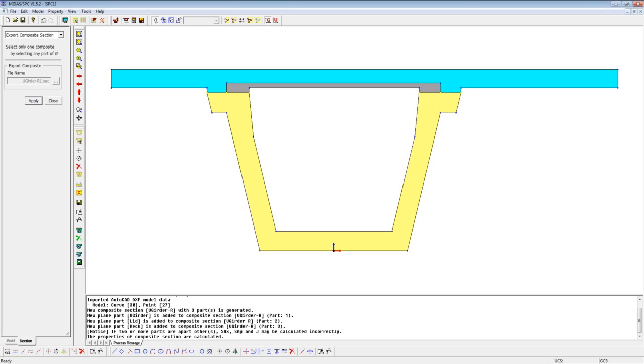Great. Another question that is coming in. Can we use rigid links instead of dummy elements? Rigid links shouldn't be used because they are infinitely stiff, and what they really do is transfer the entire load from one source to another, which is not the true behavior of the deck, because at any given time the force is being transferred through the member whose thickness is this much only. So the section stiffness is overestimated if you use a rigid link to connect the two lines of the girders.